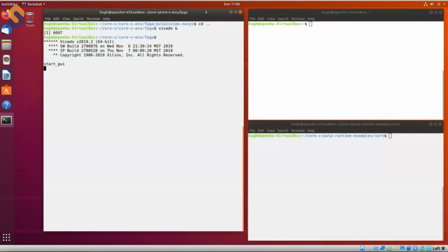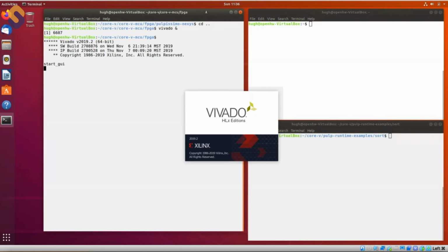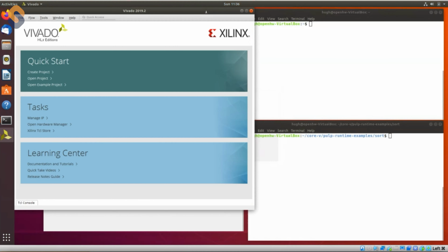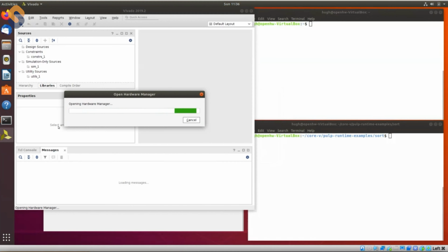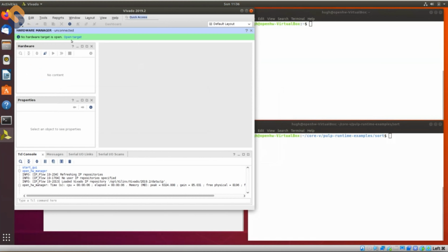There may be a trick when programming via Vivado. There are two modules, two targets within the chain, and depending on how the USB ports are configured, it may fail through auto connect. So you go in to open a target and auto connect.